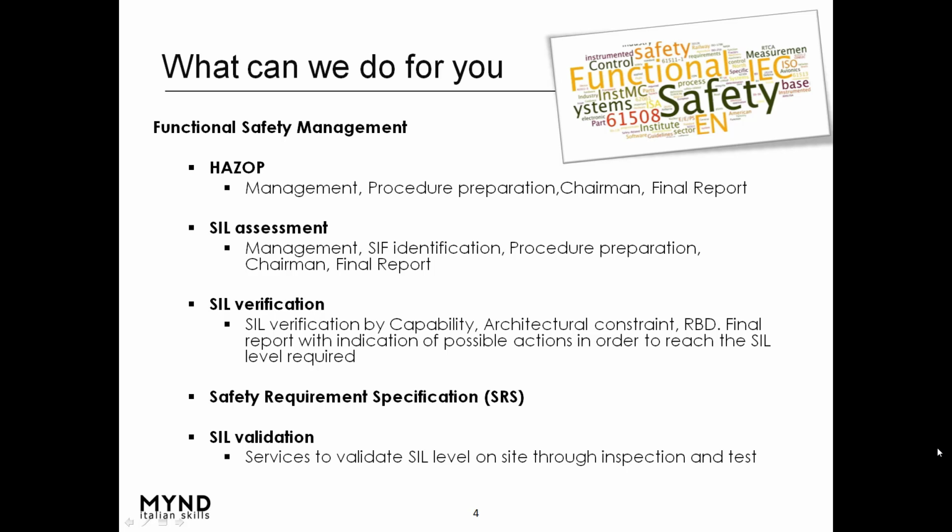For the management of functional safety, we can deal with all aspects concerning the HAZOP study, the study of SIL analysis, and therefore management and identification of safety functions, the preparation of procedures. We provide qualified chairmen and also, of course, all the final reports. Important point is that having experience also for technical automation and instrumentation, we develop SIL verification through capabilities, architectural constraints, and the calculation of the PFD, the probability of failure on demand.